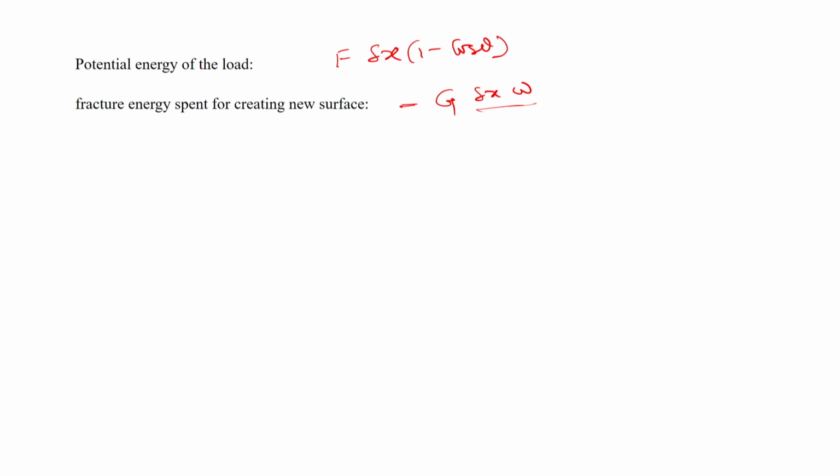G is the actual energy that goes into the interface for separating these two adherends, and G therefore is not only this thermodynamic work of adhesion, but also contains some other aspects it has to take care of. For example, the energy dissipation or irreversibility in this system, either at the surface or in the bulk, okay. G has to take care of both. So, G is not exactly the work of adhesion. G becomes equal to the work of adhesion when there is no dissipation, okay.